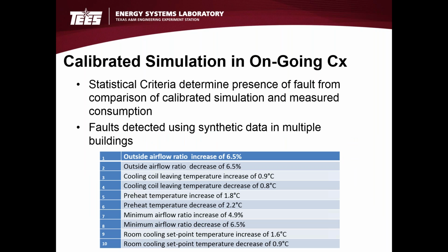Now, when we look at the use of calibrated simulation in ongoing commissioning, we talked about how we can detect changes, and we've moved on from simply looking at deviations between the calibrated simulation and the measured consumption, and have developed statistical criteria.